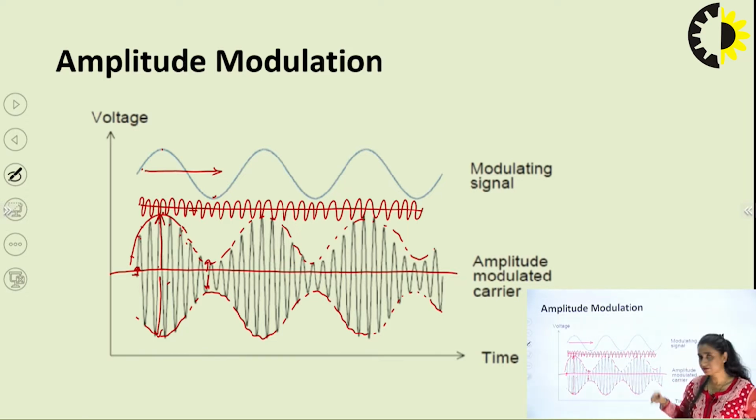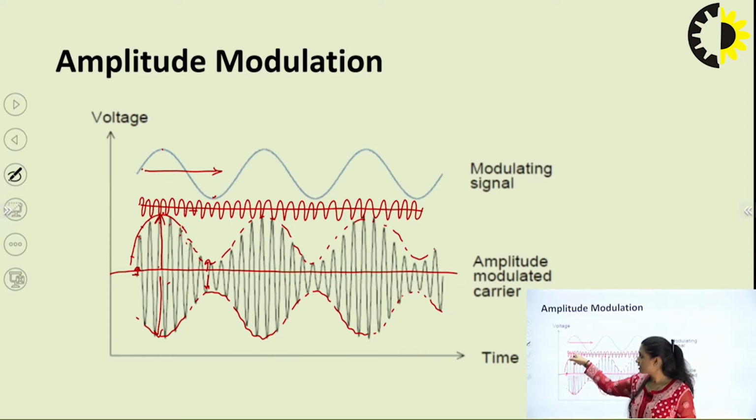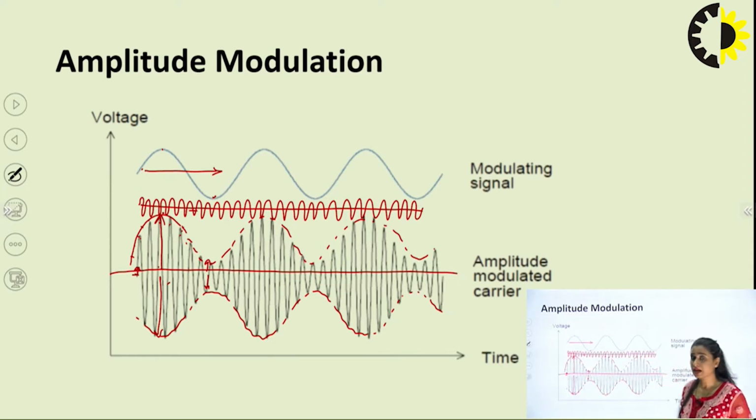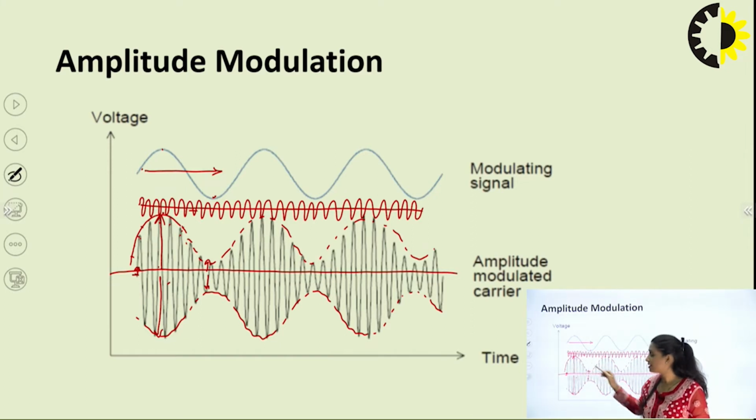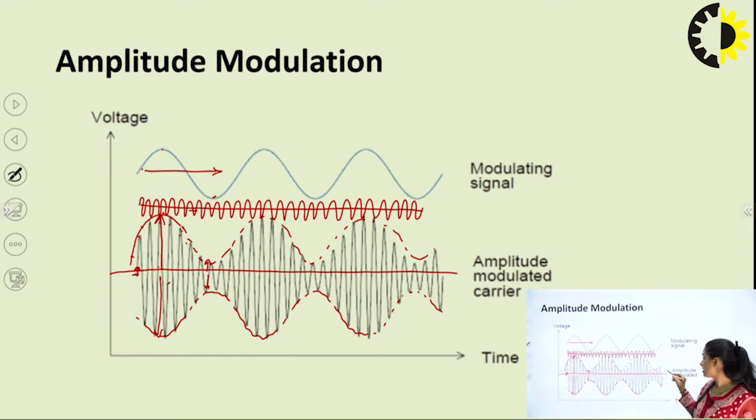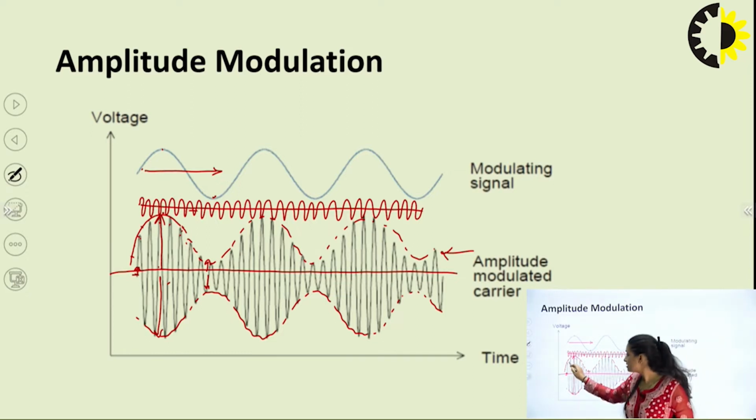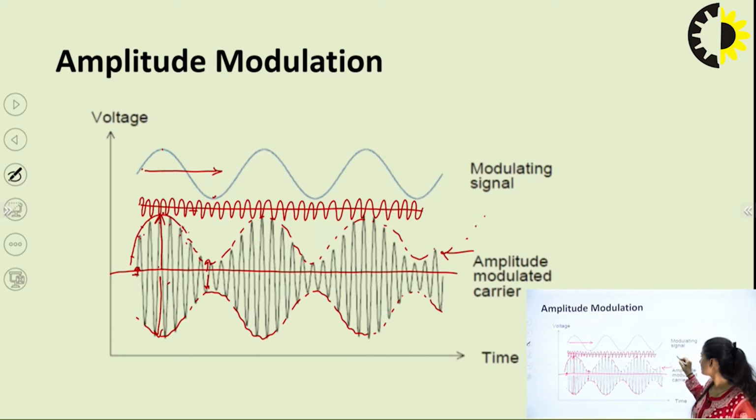This is the modulated wave, right? Here somehow the carrier takes the identity of the message signal, and where is the identity taken? In the amplitude. Because at the receiver, if I draw a circuit intelligent enough to read the peak values of the message and plot the wave, reading the peak value and plotting it back will retrieve my message signal.